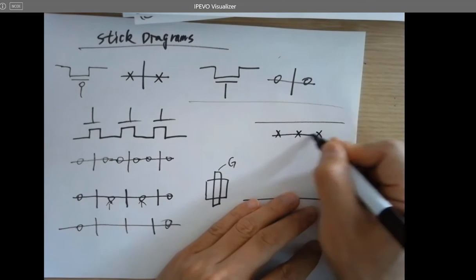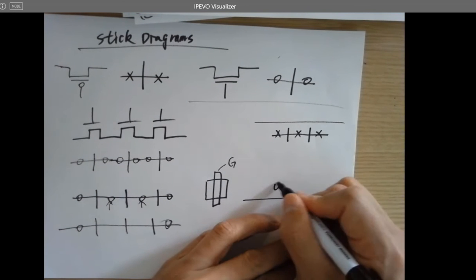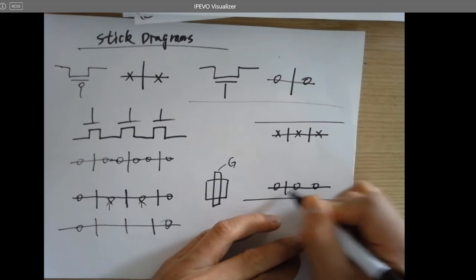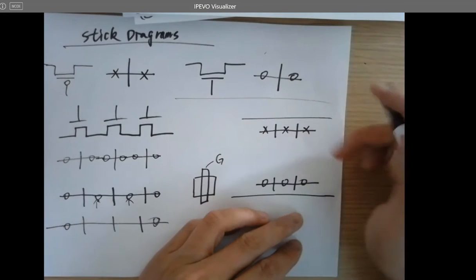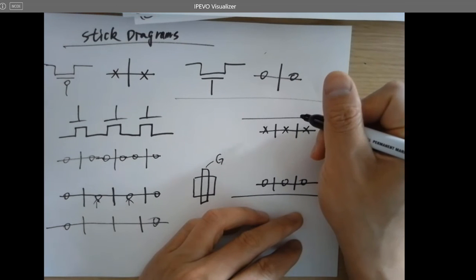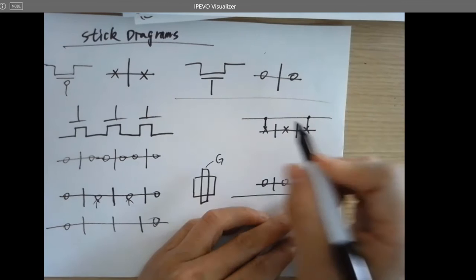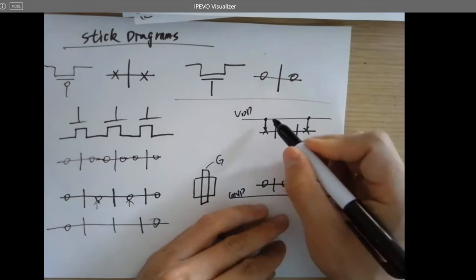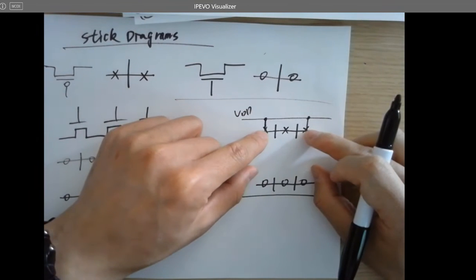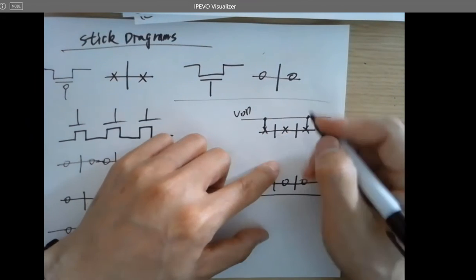I'm going to do this, 1, 2, and two NMOS, 1, 2, and the two PMOS on top are in parallel, right? So here are the two metal one lines connect to the power, that's VDD, that's ground. And these two lines will be merged here at one point.